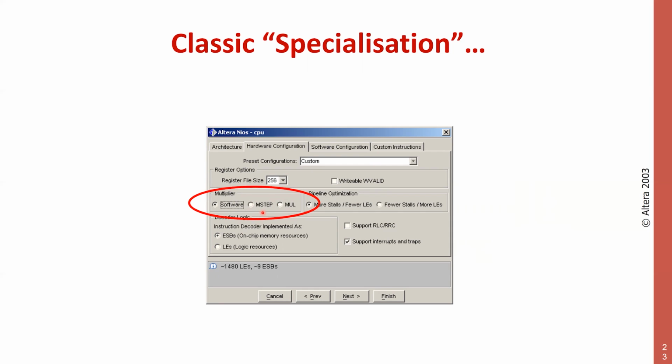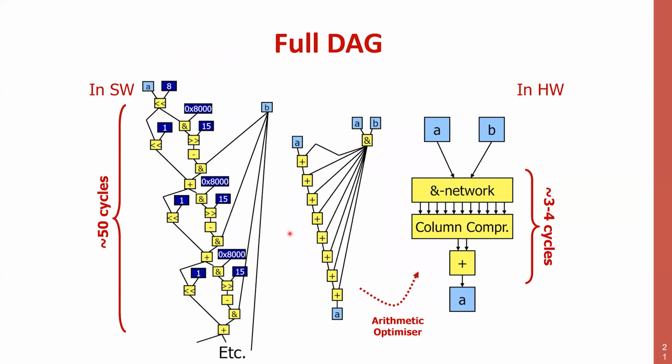The point of this exercise, and I hope that it's valuable for you to have spent this time, is to understand, why do I gain? Why is it better to have a multiplier in hardware with respect to doing it in software? I mean, everybody gives this for granted, but two things I think are to remember here. Why do I gain? Because I have new ways to exploit constants, because I have new ways to represent operations, or different ways to do operations where I restructure this tree, this addition tree, in different ways where I gain